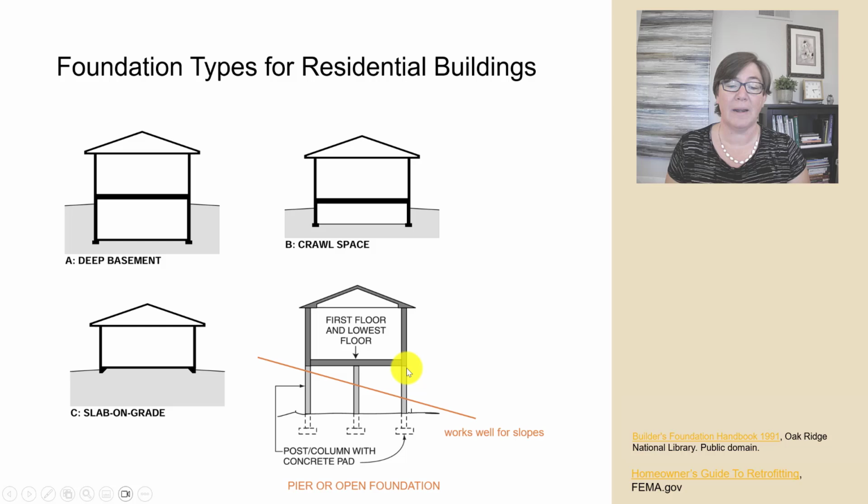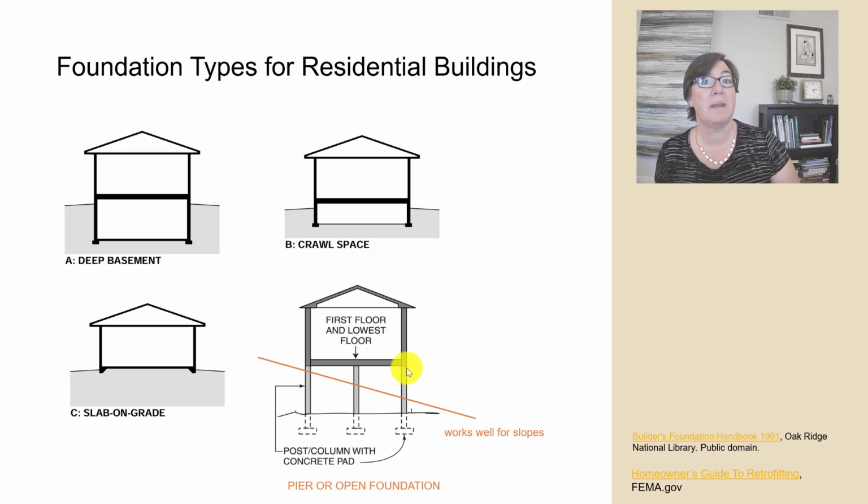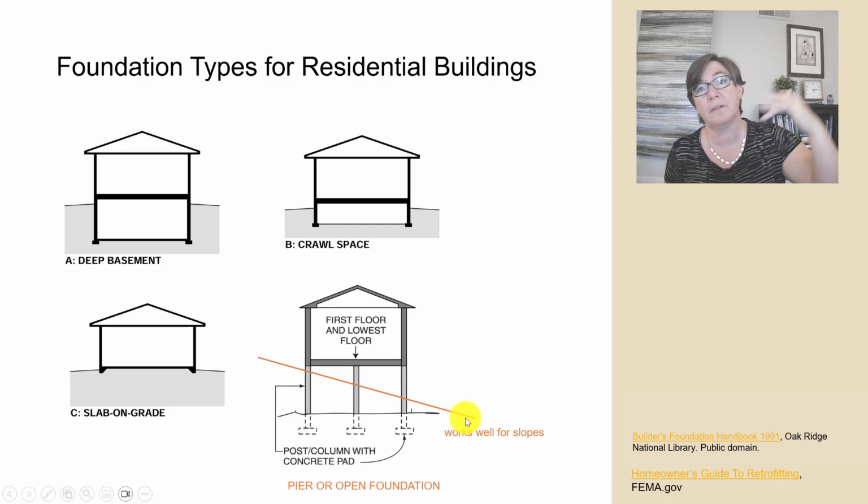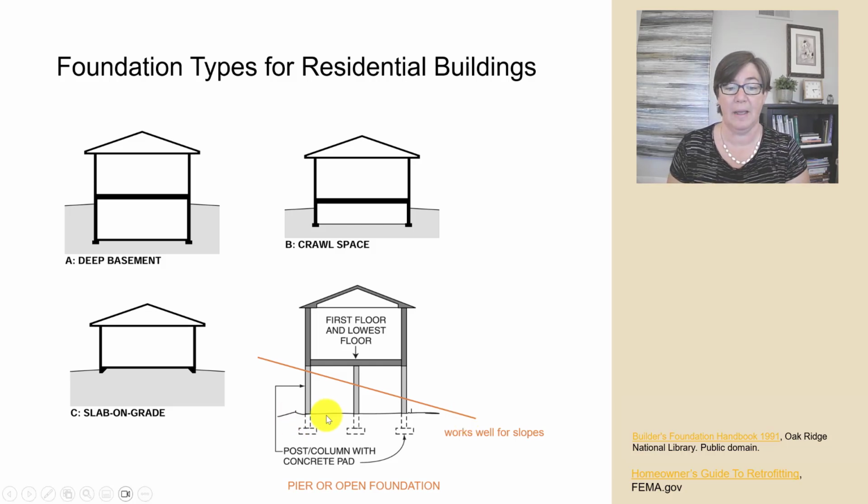And our last one is called a pier or an open foundation. This works really well for slopes and also for areas that are prone to flooding. And so you see I've placed this line right here that shows how that would work on a sloping grade rather than here with a flat grade.